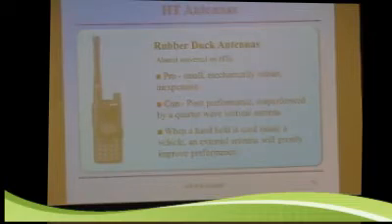Now, if you're going to be inside a car, you do not want to use your rubber duck inside a car. What is a car? It's a metal box with a couple of windows and whatnot. I used to travel quite a bit, and I had a little mag mount antenna that I would put on top of the rental cars, and I tied into my handheld, and I had a really good job. In fact, that's what I had when I was talking about being in Calgary, Alberta, Canada. A handheld with a mag mount on the rental car. That makes a tremendous difference if you want to talk to somebody from inside your car. Get, at the very least, a mag mount antenna. Get your antenna outside the metal box, and you'll do much, much better.